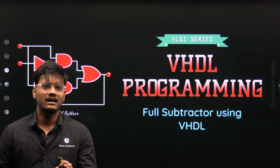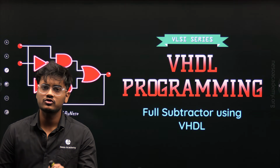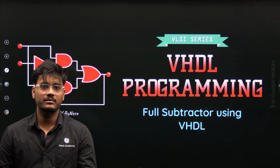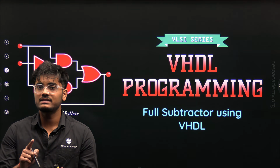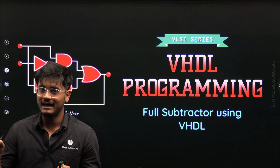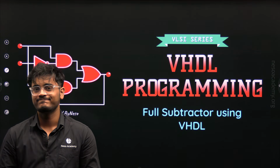Now, just like a half adder had a limitation, the half subtractor also has a limitation. A half subtractor can only subtract two single bit binary numbers without considering the input borrow from the previous stage and generate the outputs difference and borrow.